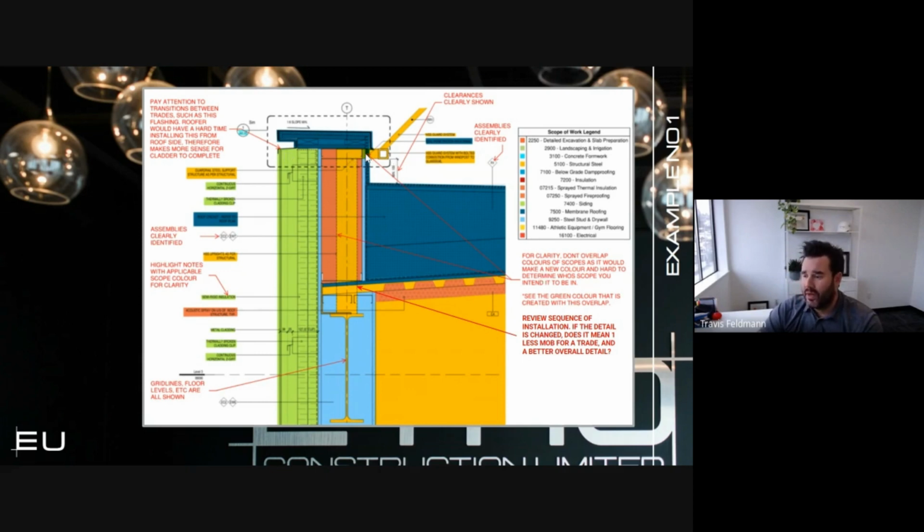You've got to watch out for, when you're coloring these drawings, your color overlap. So you actually have to plan out where you're going to color certain markups, because as you can see here, obviously there was an overlap of the yellow and the blue. This is a very visual document, so we want to make sure that if there is any ambiguity in the color and say, this green now looks for whatever reason to be this green, obviously it's not a siding element, but that's where the confusion can start to creep into a document like this. So making sure you're consistent with your coloring and where you're delineating the scope and not having that color overlap, so the intent is clear when you look at the drawing.